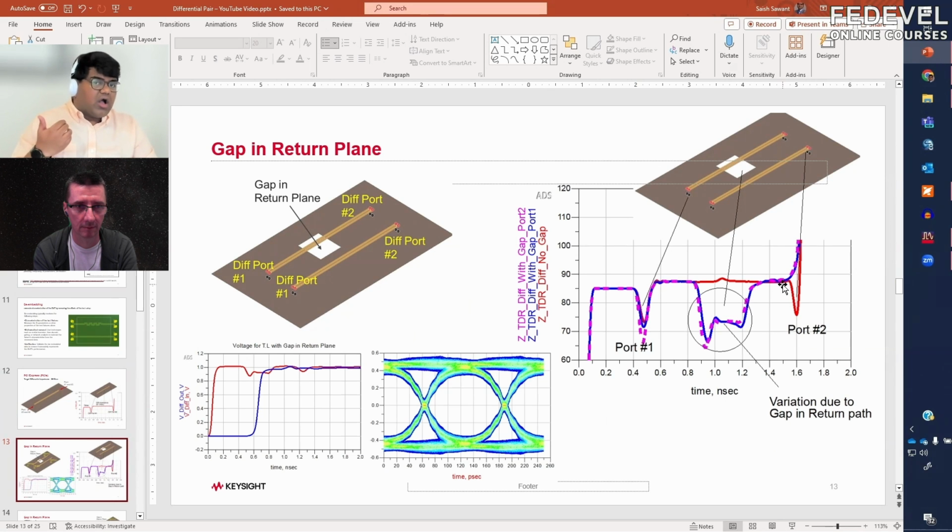It's just how this transition is happening, recovering from that and simply going to an open. So basically, if you were to speed up the rise time, then you would see it. Yes, but for that you will have to do an EM extraction up to a higher frequency, or a measurement up to a higher frequency, because that is a relation, right? Bandwidth and rise time. And it takes longer. Yeah, it would then take longer and all of that.